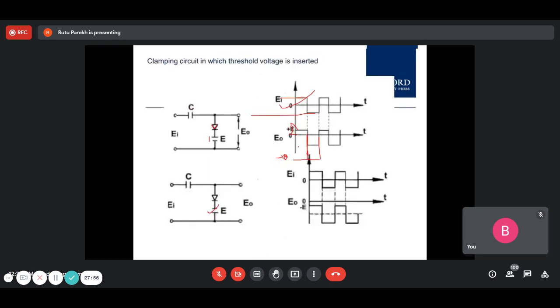And if this is positive, then you move that much up and you subtract from this lower one that much. So peak to peak should be the same as your original waveform. Now if this is minus, you go that much down again. If it is minus 1, then you move the whole waveform. This will be minus 1, this will be minus 11 then. So minus 1 minus of minus 11, the peak to peak is 10 volt.